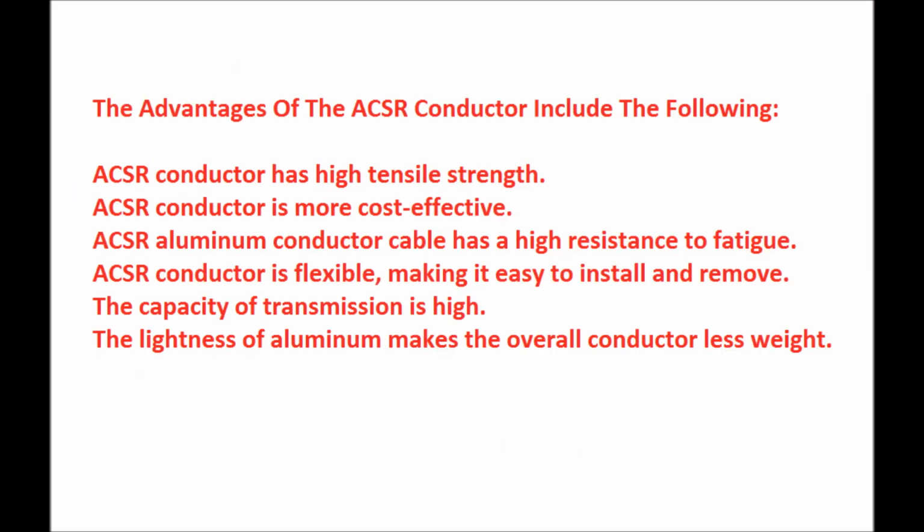So what are the advantages of using ACSR conductor? Number 1, ACSR conductor has high tensile strength. The steel in the central part provides the tensile strength for carrying the load of the conductor, and the aluminium in the outer part provides the conductivity of the conductor. Number 2, ACSR conductor is more cost effective than copper conductor. Number 3, ACSR aluminium conductor cable has a high resistance to fatigue.